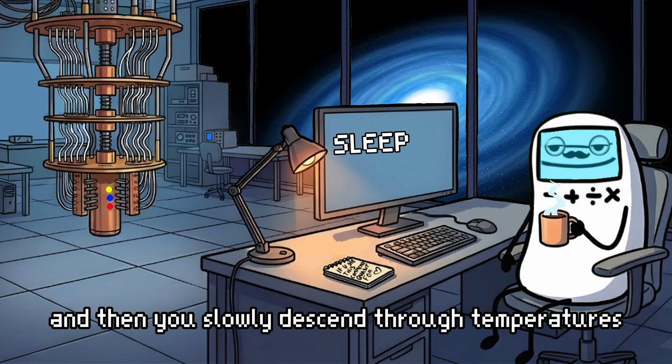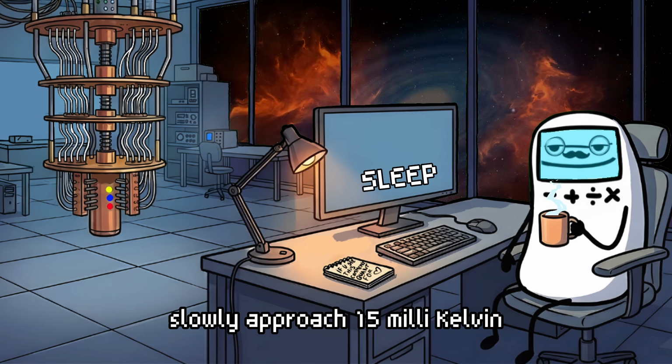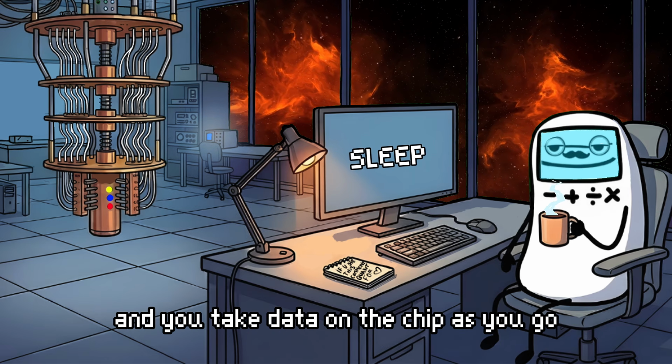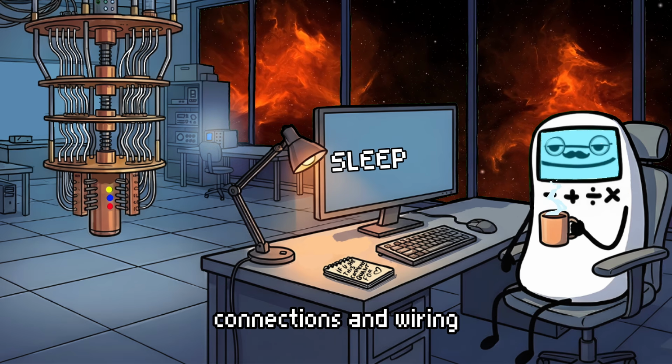And then you slowly descend through temperatures, watching the thermometers at each stage drop, watching the mixing chamber temperature slowly approach 15 millikelvin. And you take data on the chip as you go to make sure nothing went wrong with the thermal connections and wiring.